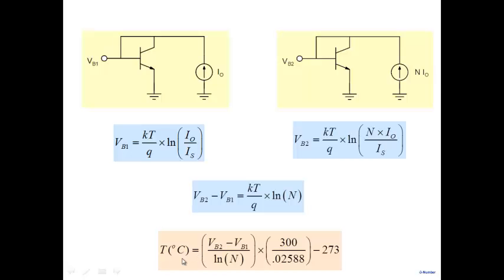So that was the idea behind measuring the temperature in the lab. Taking your bipolar transistor, passing a current I0, then passing maybe one could choose a current of 1 microampere, choose a current of 100 microamperes or a milliampere, measure VB1, measure VB2, subtract and calculate what the value of the temperature is. Okay? Looks fine?